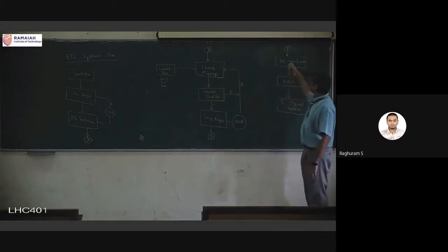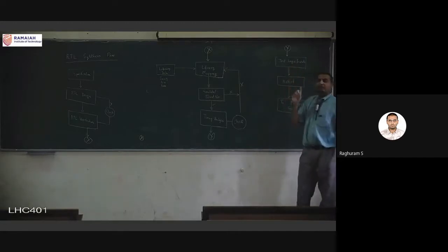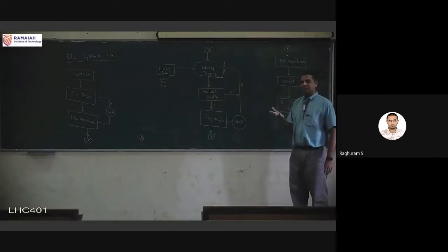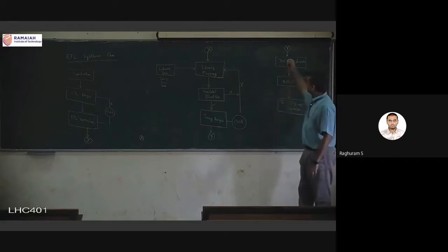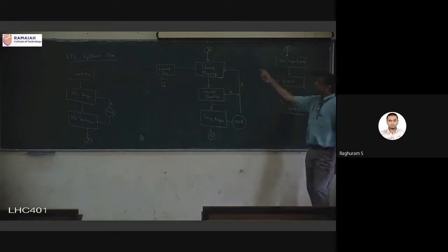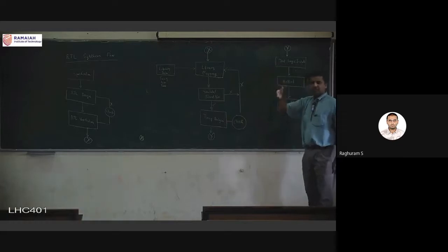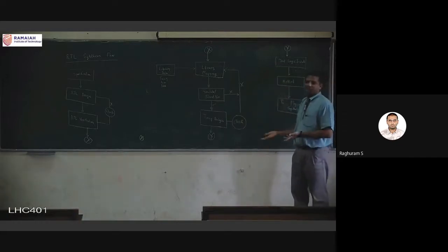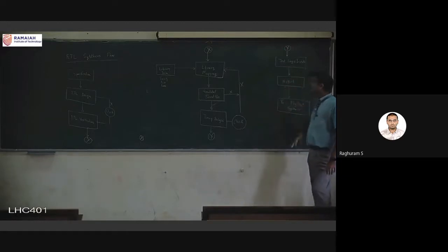But this is the key point for post silicon. After the actual silicon is there, there are many things that they check, but one of the most important things is testing for fabrication errors, and that is also inserted as part of the front end VLSI design, because these are also logic gates. Anytime you're putting in logic gates, you have to put the test logic also. And then you get a new netlist.